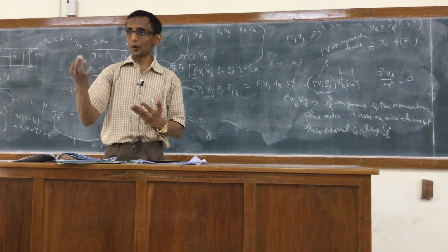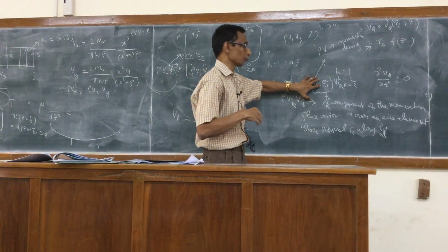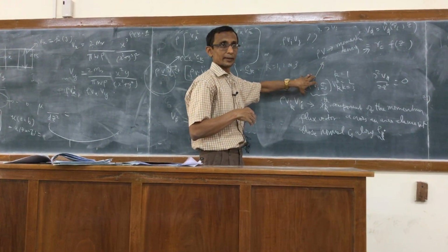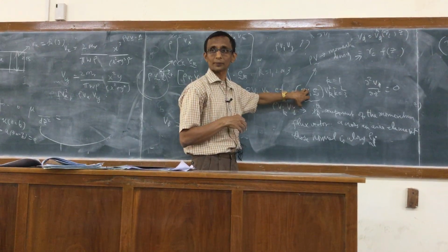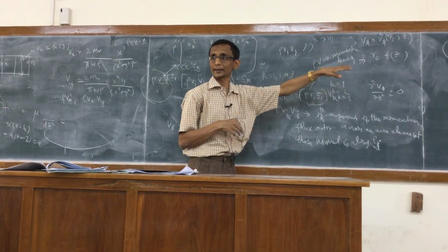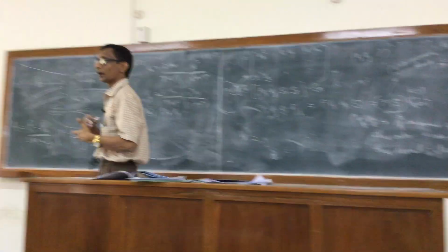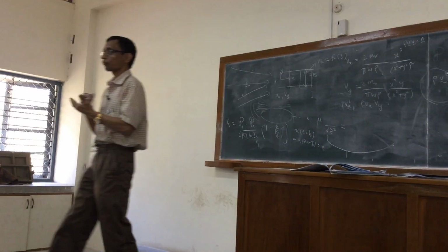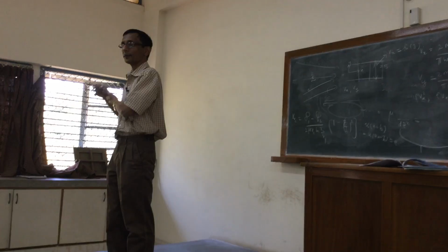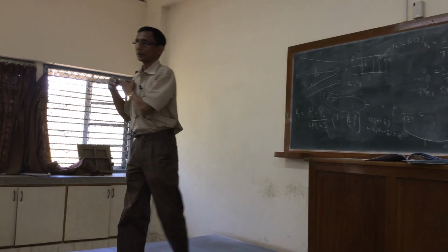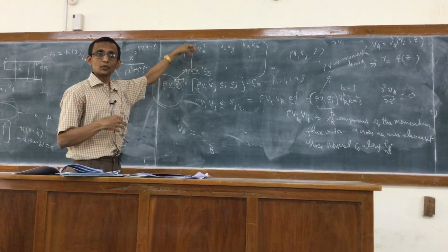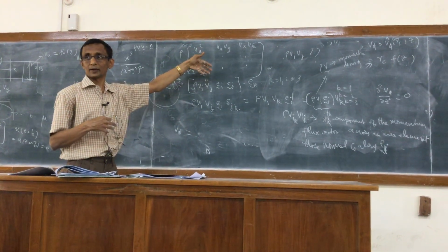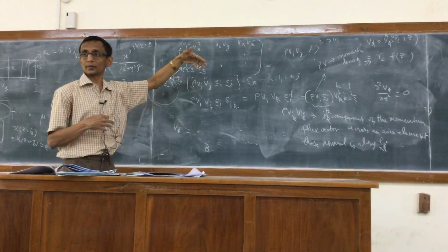But one index certainly corresponds to the momentum flux density at a given point, and the second index corresponds to the area element, because what we are looking at is getting a tensor from a vector. The tensor merely serves the purpose of getting you the momentum flux vector, which is of utmost importance.